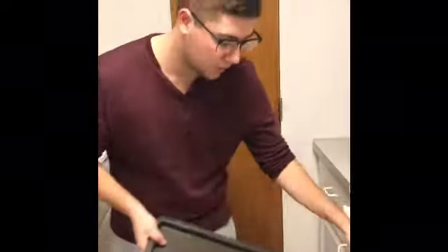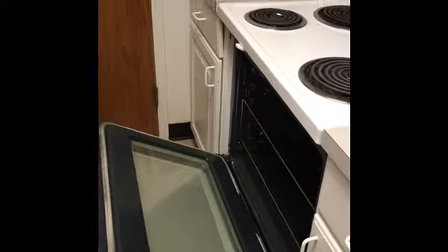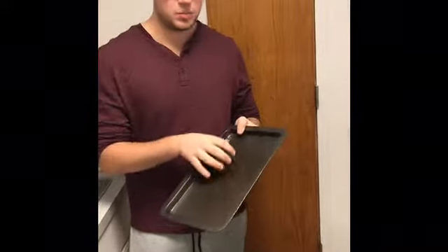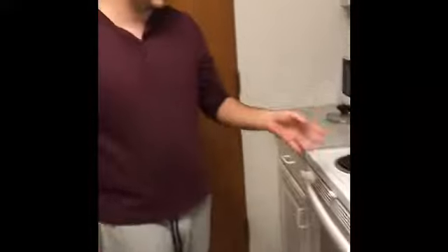So in this oven right here, as I mentioned, you have the area, which would be the area of the oven, and we have our plate, which we're going to take as the temperature of the surface, so the temperature of the surface of this plate. And then when we close the oven at our set temperature, T infinity, which is 200 degrees, we're going to be able to find the heat transfer rate or the heat transfer flux.